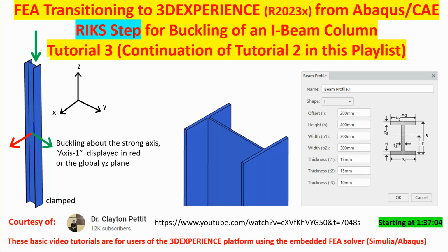Now, if there is any nonlinearity involved, such as imperfections, material nonlinearity, contact, etc., the result of a linear buckling analysis is just not valid. And you have to do a nonlinear analysis, and nonlinear analysis needs to be done with the RIKS step method.